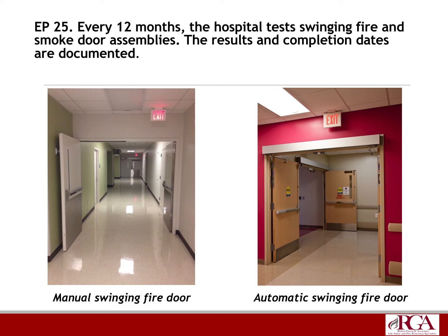And that's where the future of fire protection testing is going. It's integrated testing, because you have different folks with different skill sets that are checking different components, but ultimately, are these components and these life safety features, are they going to work during an actual fire? And that's really what you want to check. But going back to simulating a fire condition, you pull the power off the header, you pull the power off the crash bars.